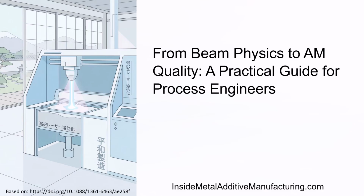Laser powder bed fusion has matured rapidly over the past decade, yet most process optimization still revolves around familiar variables such as laser power, scan speed, hatch spacing, and layer thickness. If you have ever observed two parameter sets with identical energy density producing completely different melt pool behavior, defect populations, or residual stress states, the underlying reason is often not power or speed, but the shape of the laser beam